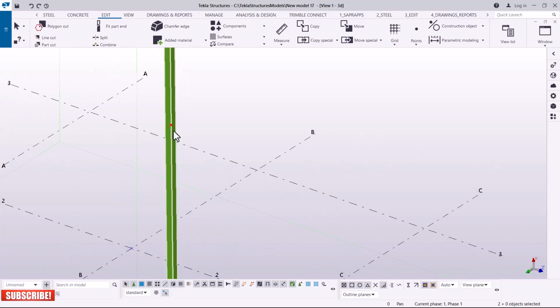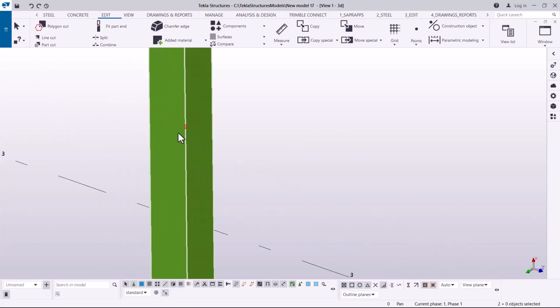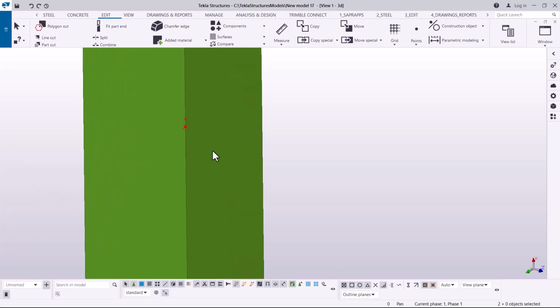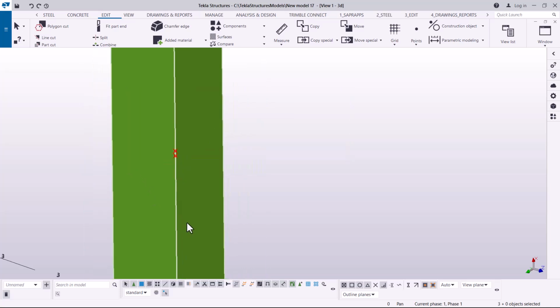I want to retain my height as a constant of 6 meters, with a 10 millimeter gap included. So I'm going to select this point. The initial ones I had gotten rid of because we were not getting the actual 6 meters; we were getting less 10 millimeters. So I'm going to add that 10 millimeter so that when we split it, we'll have a 6 meter length of our steel.